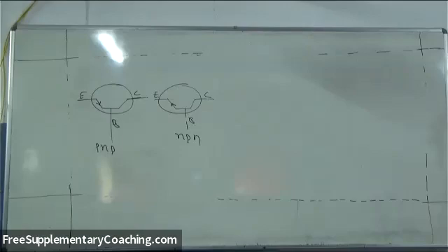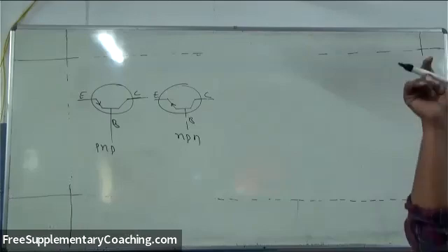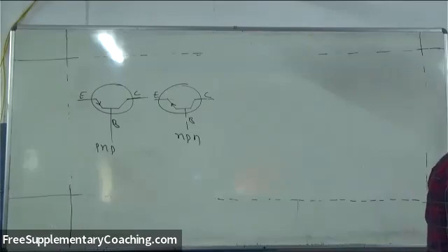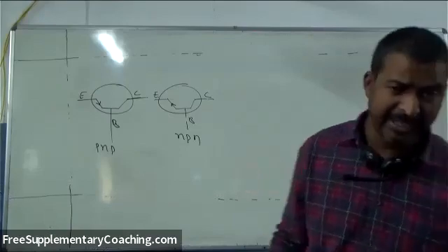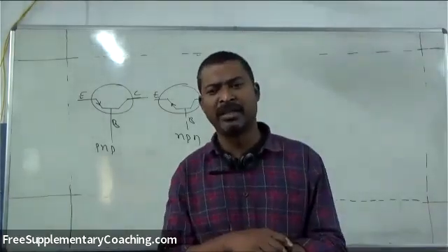And what is PN junction diode? Define depletion layer. PN junction diode is what? One P-type semiconductor and one N-type semiconductor are joined together. A junction will be formed and we call it a PN junction diode. And there is a thin layer in which immobile ions will be there.